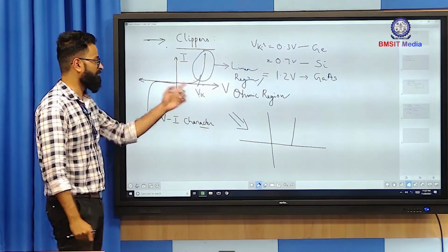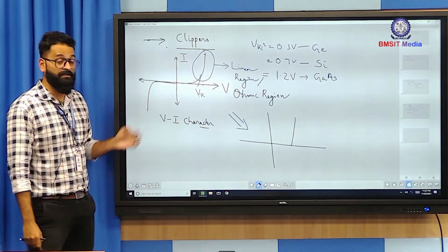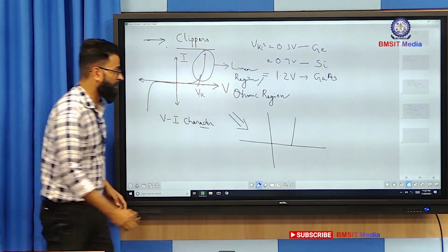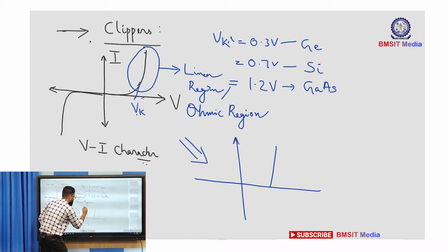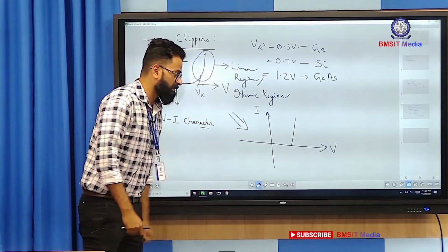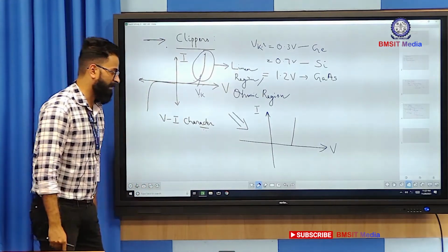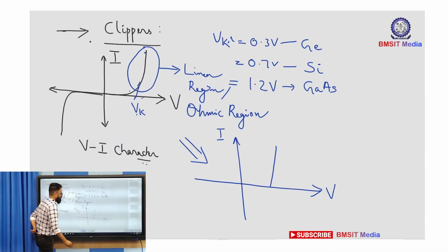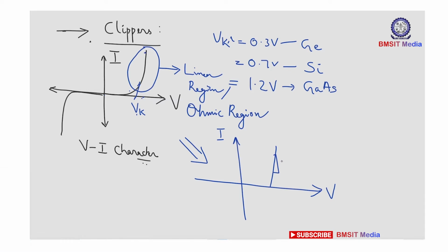So what we have done is we have discarded the transition zone area, and this being I and this being V. Okay. So this is called as piecewise linear model or first approximation. And the slope of this straight line, say delta y, delta x.